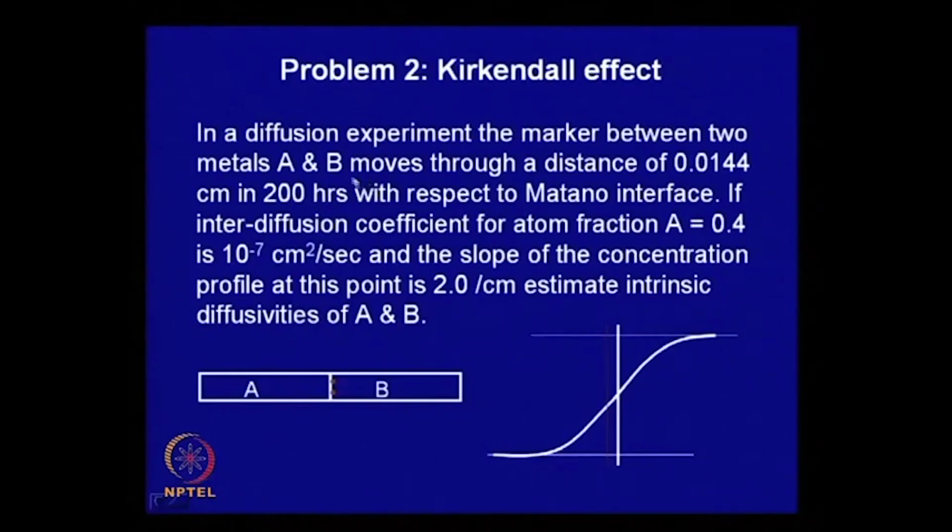Now, in this diffusion experiment, it has been found that the marker between the two metals moves through a distance of 0.0144 centimeter in 200 hours with respect to the Matano interface. So, here this is the Matano interface, this is the concentration profile, this area and this area are equal, and this is the position of the marker. So, this distance in 200 hours is of this magnitude.